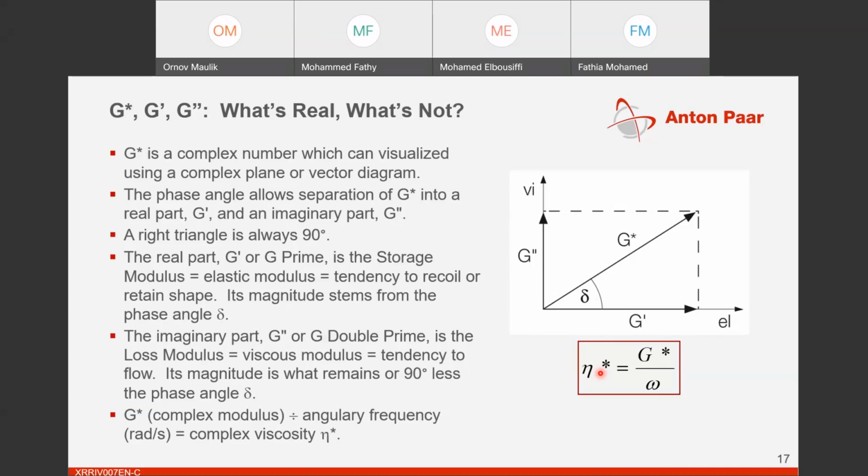If you remember, yesterday I mentioned that it is always better to do oscillatory tests on paste-like samples, because that prevents excessive wall slippage or removal of the sample from in between the geometries due to high shear rates, because we can always determine the viscosity with oscillatory tests too.